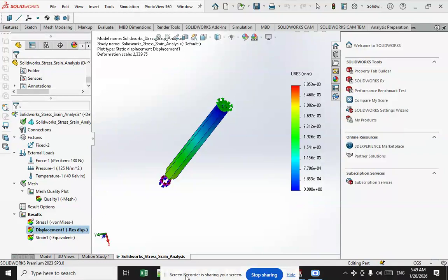From these measurements, properties such as Young's modulus, Poisson's ratio, yield strength, and strain-hardening characteristics of the sample can be determined. The next one is strain gauges. They can be used to experimentally determine the deformation of a physical part. A commonly used type of strain gauge is a thin flat resistor that is affixed to the surface of a part and which measures the strain in a given direction.